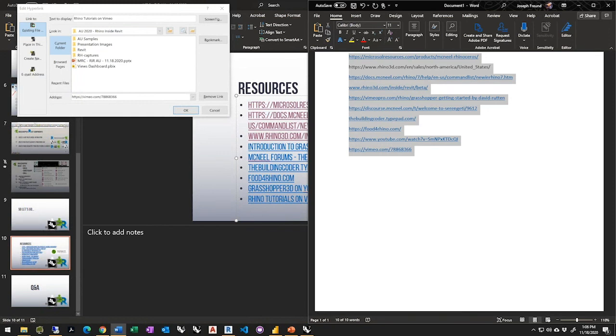Rhino.Inside.Revit doesn't really care about the extent of the model it's dealing with. They're just numbers to the program. And Rhino itself has templates for models based on different unit systems and different resolutions. So you can set up a Rhino model for yourself that's more appropriate in resolution for civil projects, and then you can continue working with Rhino inside Revit to bring all that geometry into Revit and vice versa.